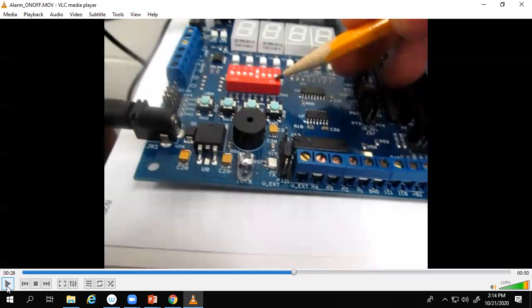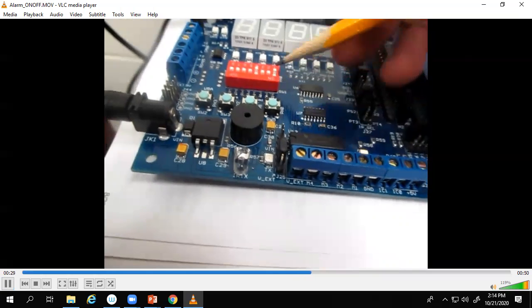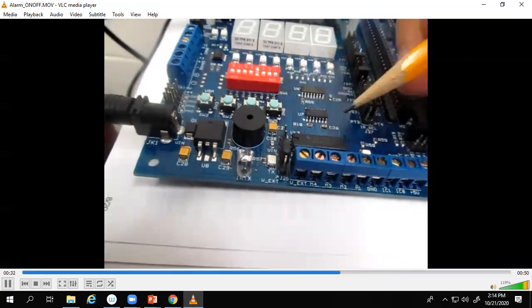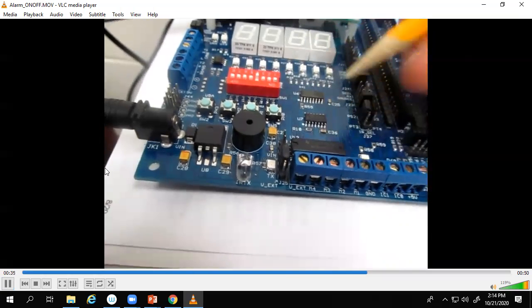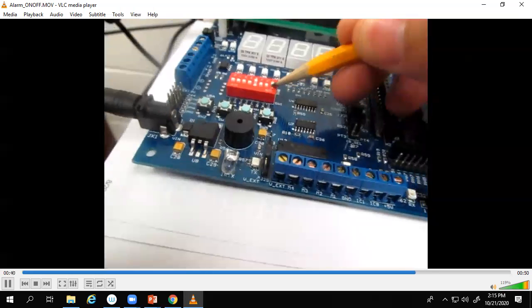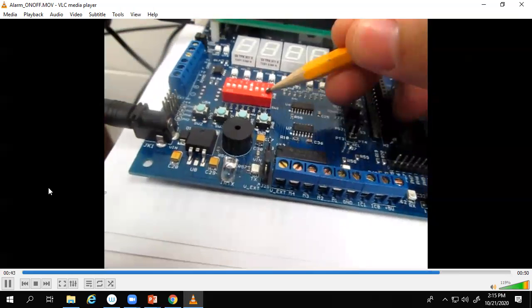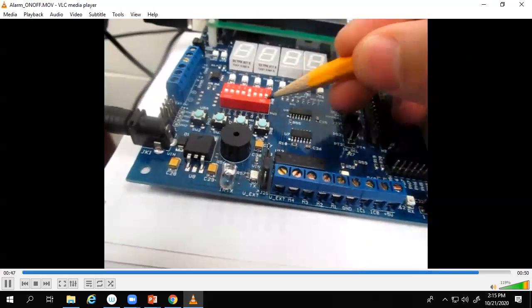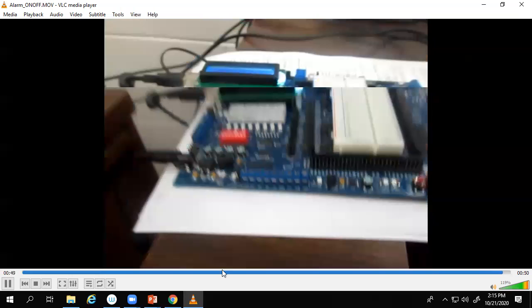By accident, there's no delay, because when I turned it off, it was at the end of 1 second, and we check every 1 second. You know what I'm saying? So it depends on where you turn it off. If I check here and you turn it off very close to that, you're not even going to observe it. There is a delay here, very little, because we check the status of the switch every 1 second. Sometimes I'm trying to make some delay, I want to make the delay, but I can't. Okay, guys, any questions?